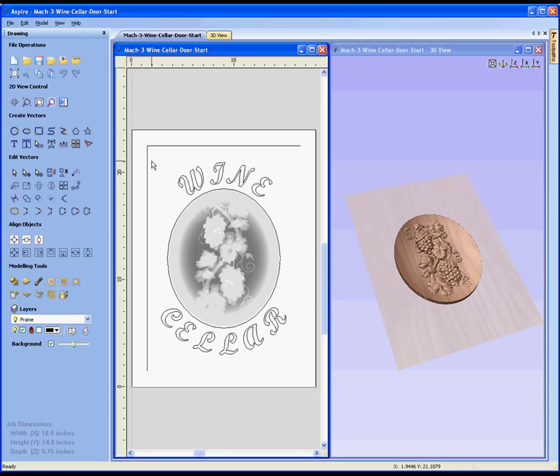I need to completely enclose the items I want to pick. Again though, if I click to the right and select upwards to the left, it will allow me to pick these without completely enclosing them, and that makes it easier to select and delete them without deleting something else that I'm going to need.